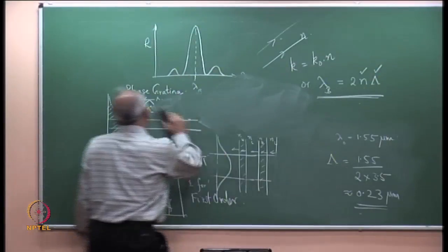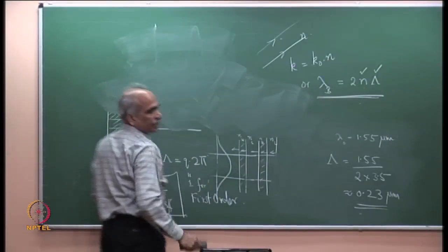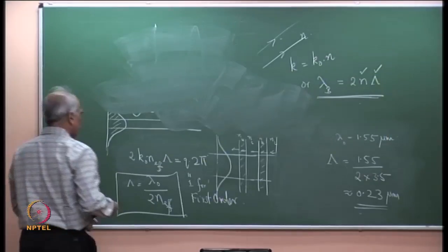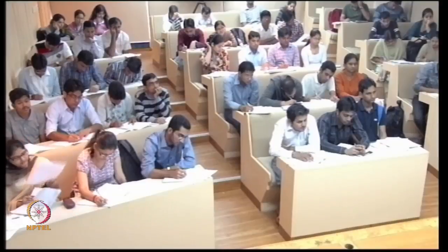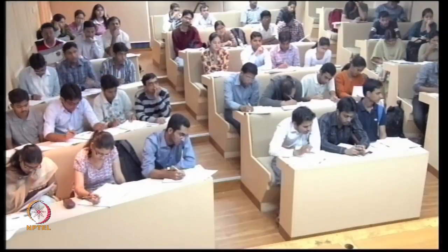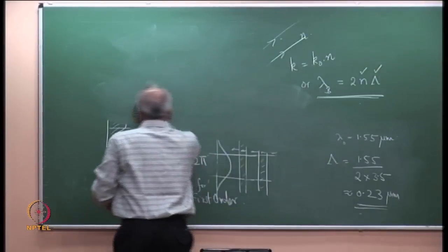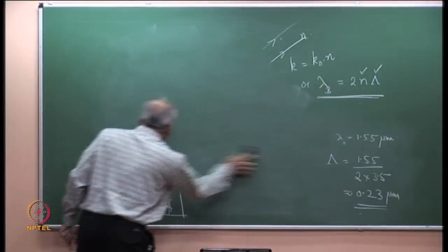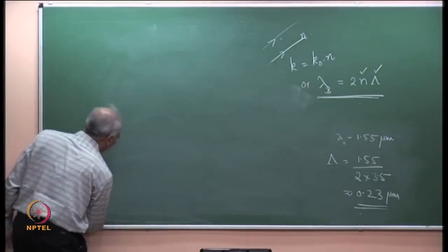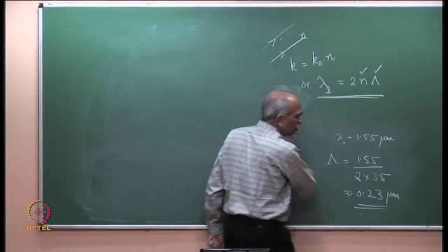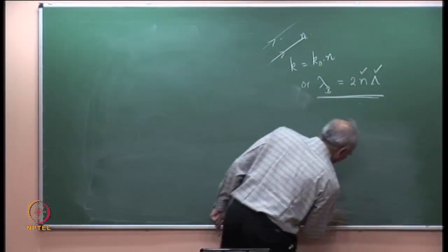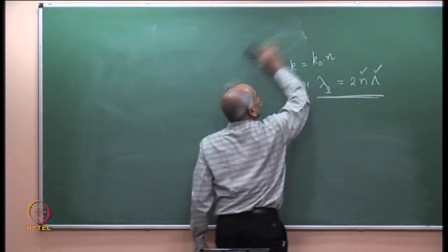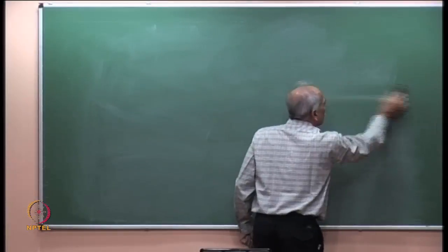There are some intricacies here, more details related to the distributed feedback laser. I have talked about the basic principle. Actually, although this is the wavelength that I have written, when you make a distributed feedback laser, if it is perfectly symmetric, then it will oscillate in 2 modes which are adjacent, and there are techniques to suppress such modes.